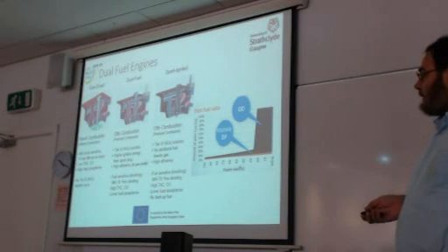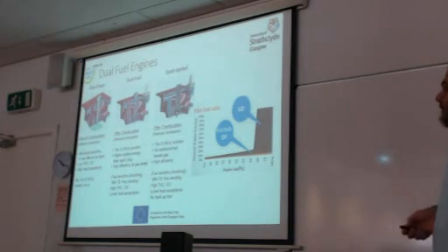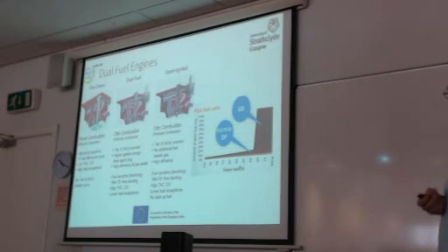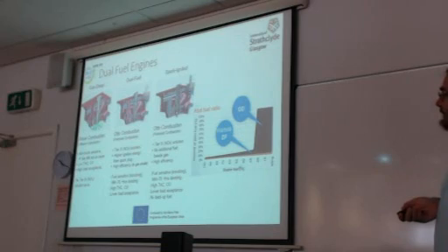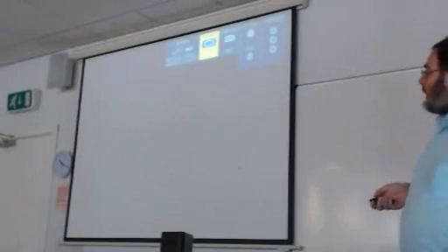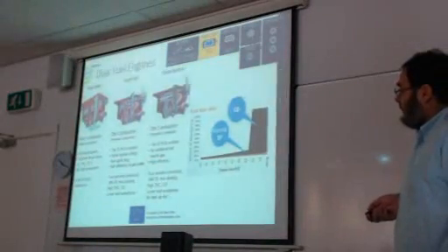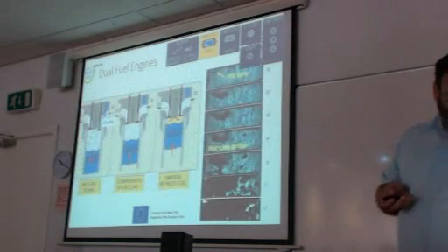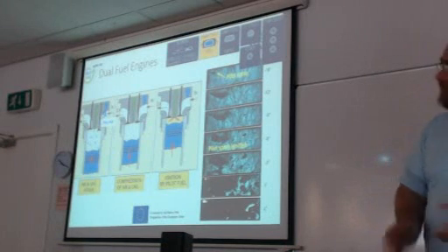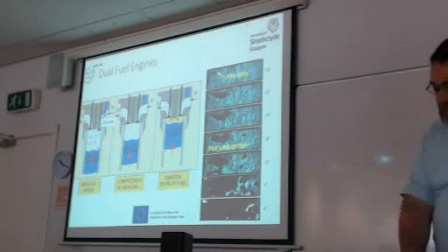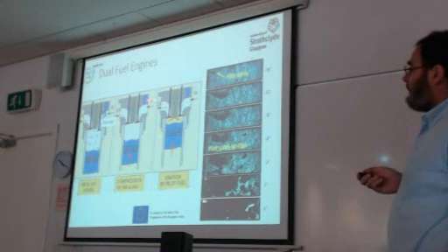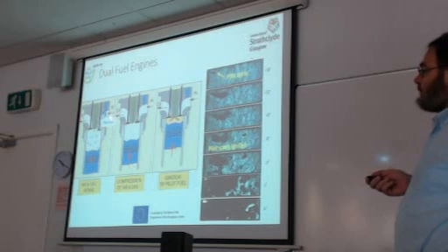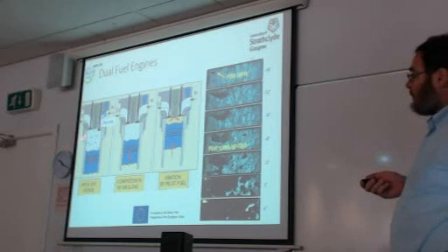Again, the methane number affects the engine operation. Hydrocarbons and carbon monoxide are high. The engine can operate at low load, but as I mentioned, there is no backup fuel, no second fuel that can be used in case of an emergency or a case of engine deficiency. So, by saying that, let's see some more details of the premixed combustion engine.